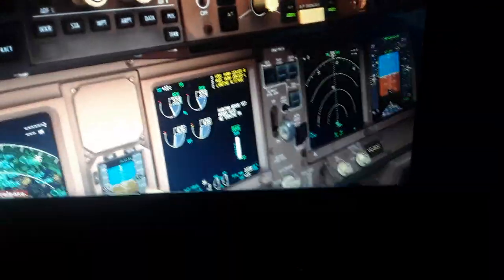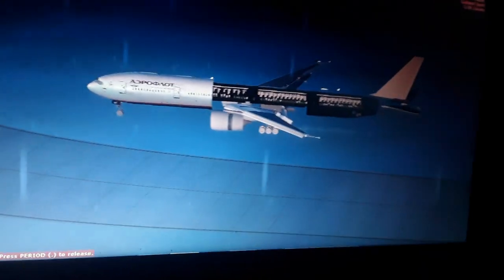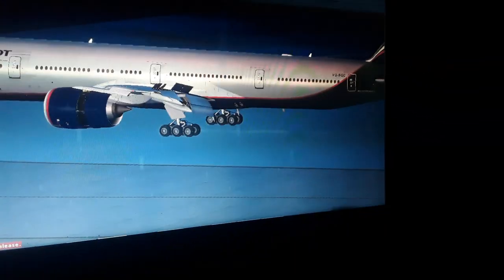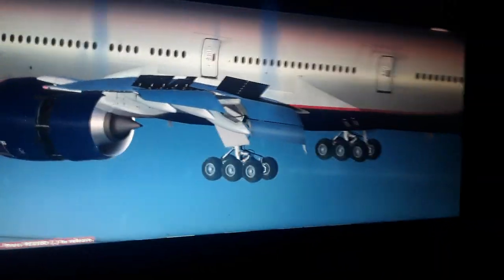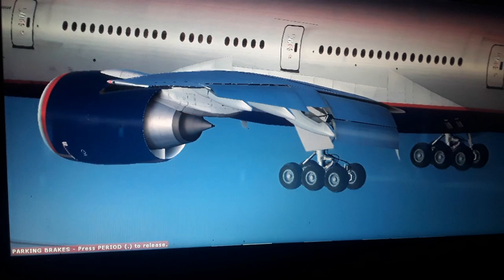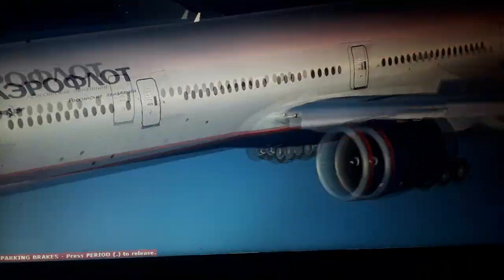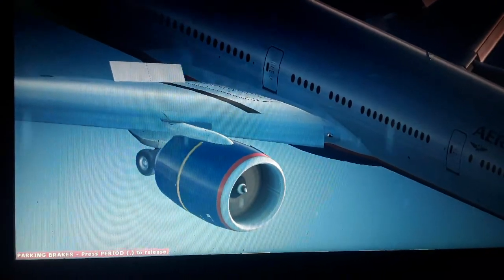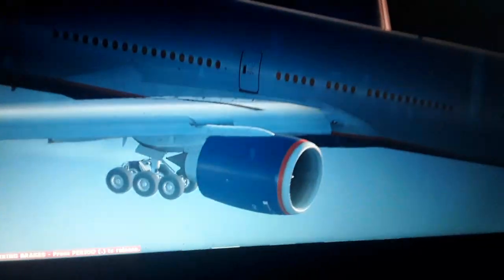So you see the thrust reverse command over here, the reverse. So this will slow down the aircraft in a landing. The thrust reversers and the speed brakes extend during the landing process or in a rejected takeoff. So you can cancel and retract and extend again the thrust reverse. Also, you see from the forward side like this, you see again the thrust reverse, retract the thrust reverse and extend them again like this.